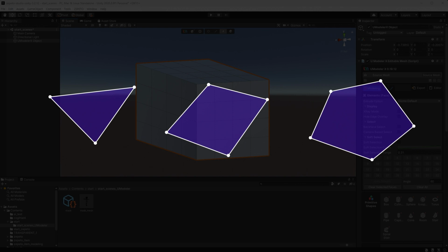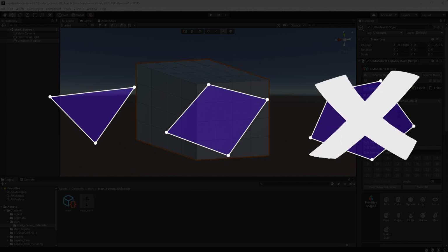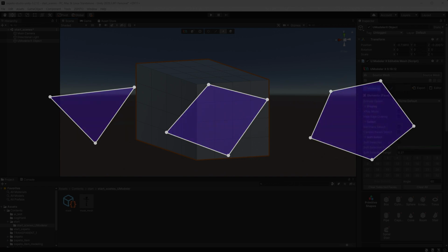While 3D software interprets objects' faces as triangles for recognition, it's much more convenient for modeling to use quad shapes rather than triangles. Thus, it's recommended to model in quad shapes whenever possible. Also, be cautious with n-gons, as they can cause issues during subdivision, UV mapping, or rigging.